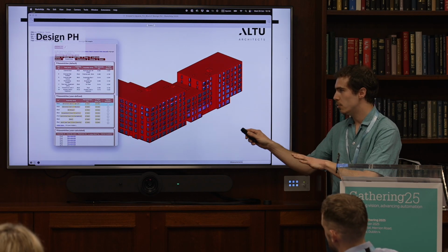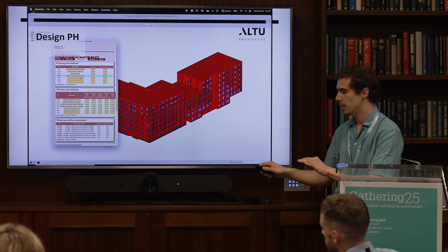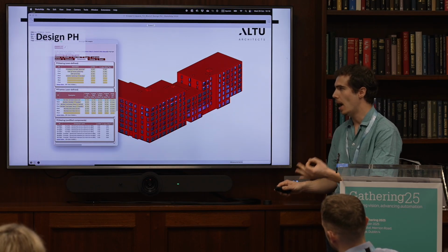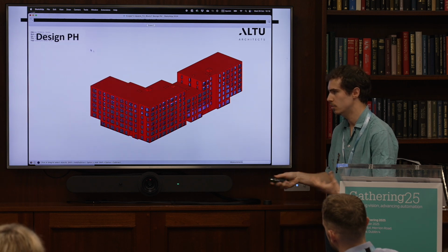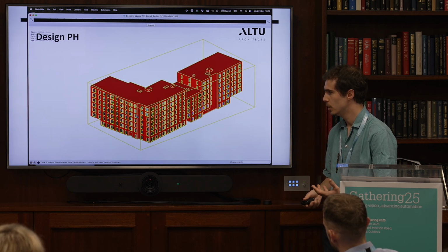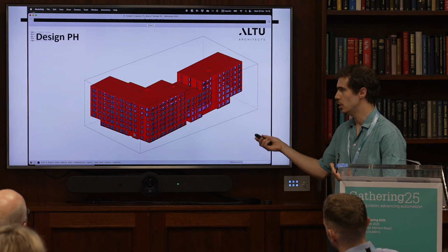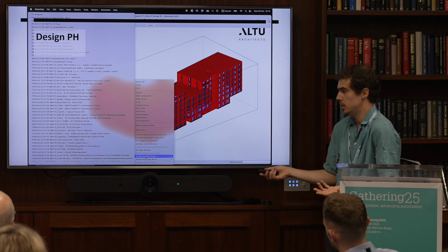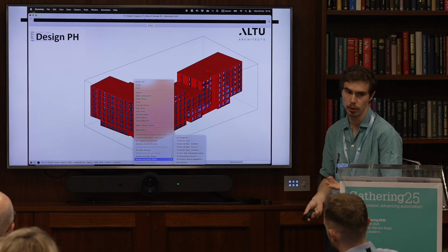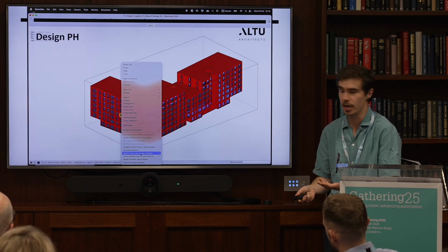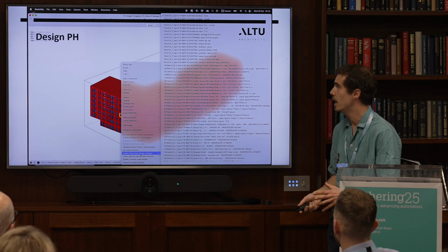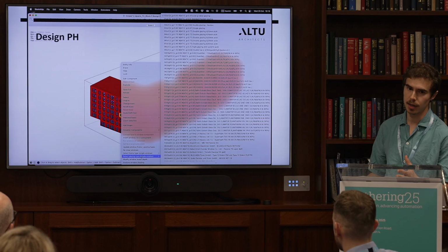and we create in it each assembly and component that we've got in our facades, roofs, floors. And we assign to each of those surfaces the type of assembly that it is going to be. So, for example, that wall will be a brick wall with cavity insulation, but it could be a render wall, and we're just assigning that with a specific U value linked to that.